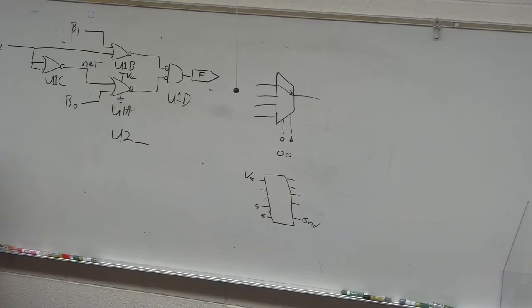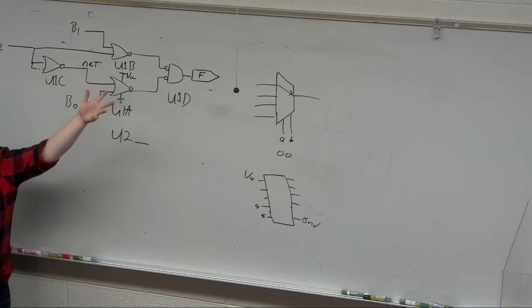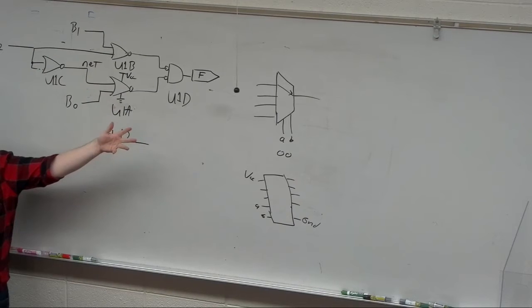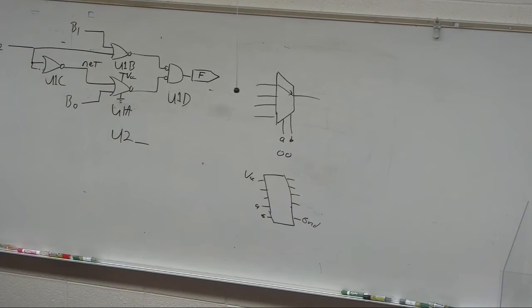And then somewhere else over here, do this. Because this VCC is the same as this VCC, they are connected together. So that's what's called a logical net, or a logical connection. It's not physically connected together, but they have the same name, so we know they're connected together. And we know that this is 5 volts because 0 plus 5 is 5.